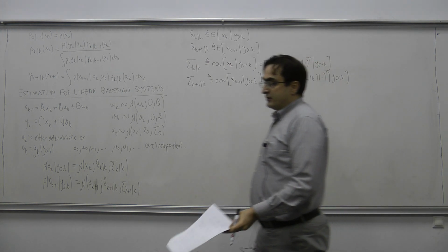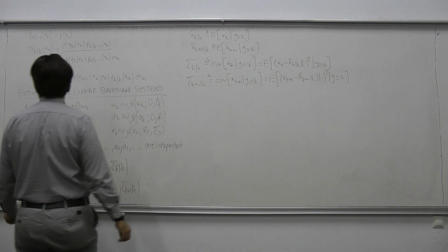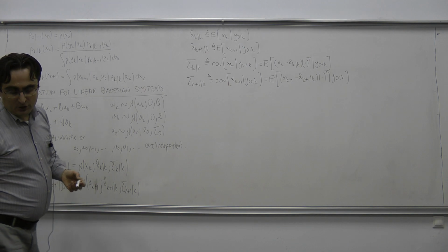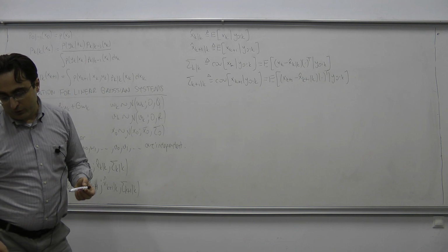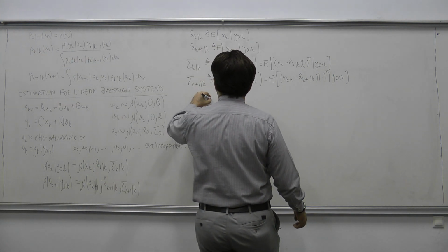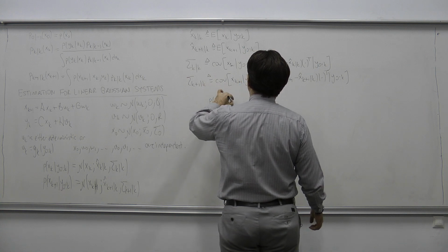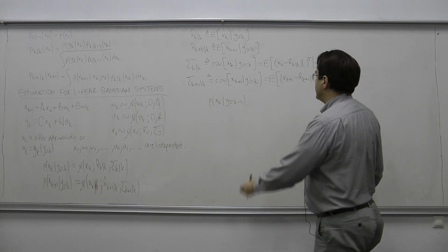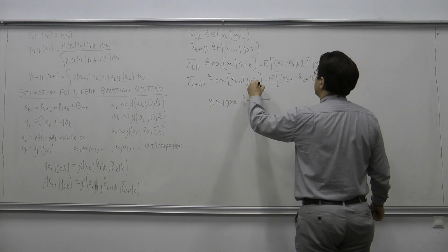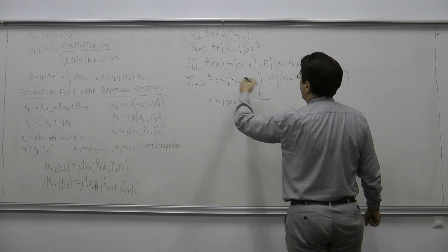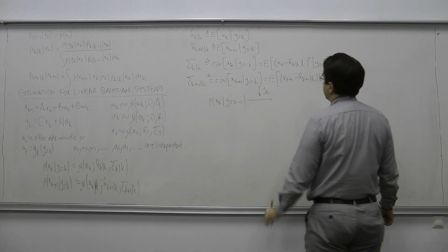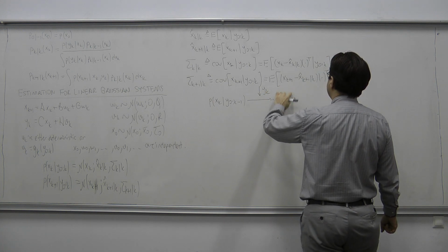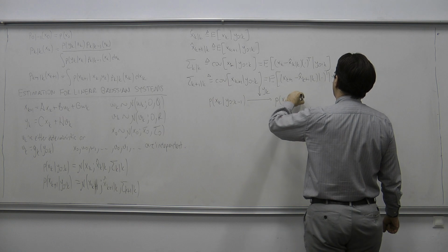So now we know that we are obtaining posterior distributions by applying such a recursion. So where do we start this recursion? For example, I can have P of xk given y0k minus 1. This is the predicted distribution in the previous step. Then I apply something called a measurement update or a correction, and yk enters into this correction, and I calculate P of xk given y0k.